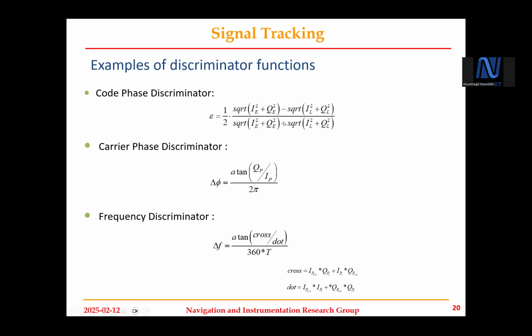This, by the way, is well known, and it is called early power minus late power. It's normalized as you see here. This is the early power: the sum of the power, or the samples, on the in phase plus the samples on the quadrature, squared, gives you the early power, and this is minus the late power. We need to keep those, as we mentioned earlier, balanced.